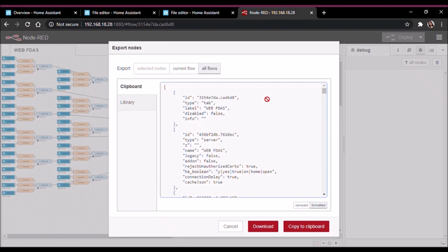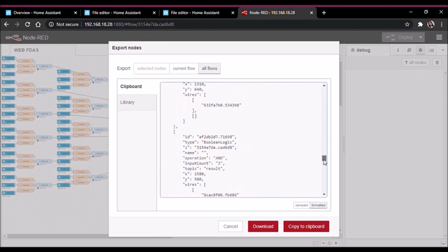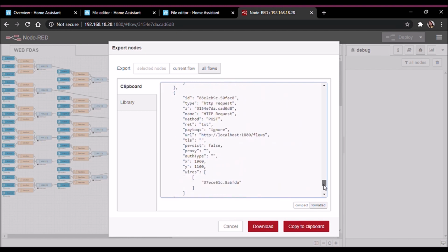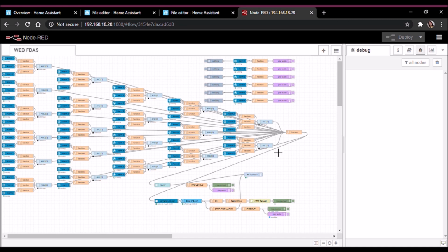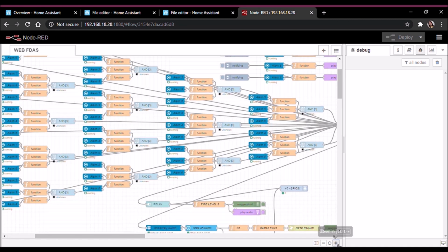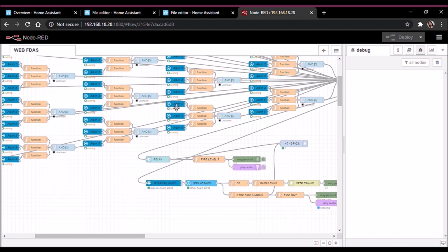The Node-RED flow for fire level 3 is programmed using JavaScript by translating our 81 calculated combinations of alarms for fire levels. Node-RED receives data from Home Assistant and translates it to 1 or 0 depending on the presence of smoke. An AND-gate node is used on combinations of 3 different alarms to know if fire level 3 is up or not.